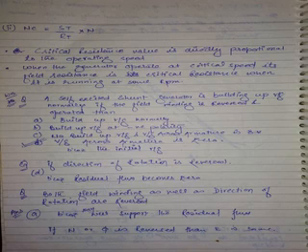Now, OCC came down at 1200 RPM. If you want critical resistance, what will you do? What is the critical resistance of the machine when it is running at 1200 RPM? Draw a tangent, right? So somewhere make a point. It is linearly varying, so let this point be this, right? Now, what is the critical resistance? Is it above that, below that, or the same value? Definitely below it. If it is 200 by 1, it is likely to be 150 by 1. So what happened to critical resistance? Decreased.